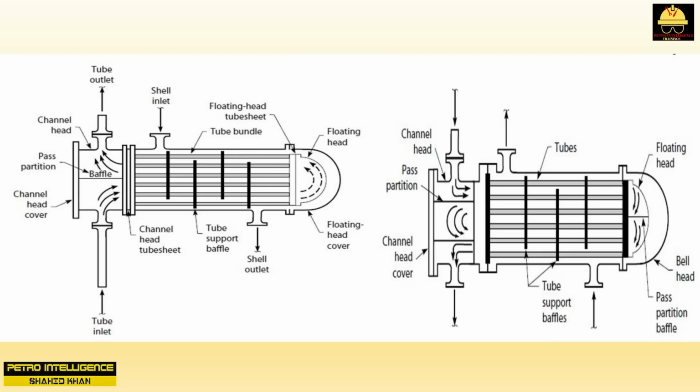Let me explain. Pressure drop increases with the square of velocity. If the velocity doubles, the pressure drop would go up by a factor of 4. Pressure drop increases directly, or linearly, with the length that the flow traverses. The fluid must go twice as far in a 4-pass as in a 2-pass tube bundle. 4 times 2 equals 8.